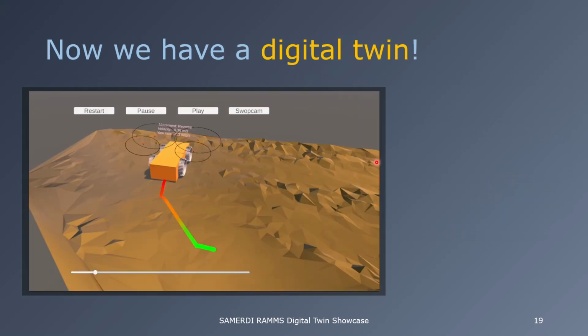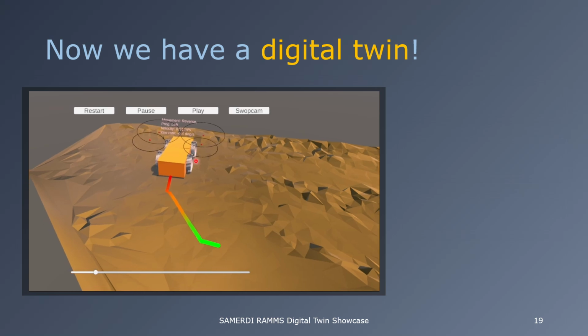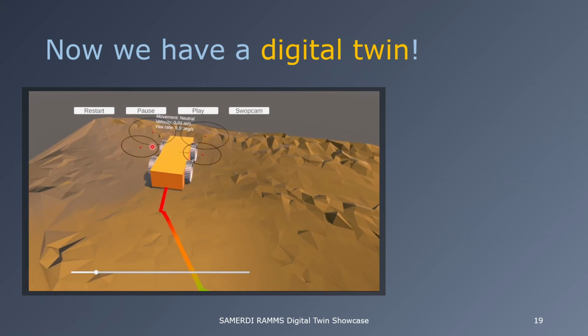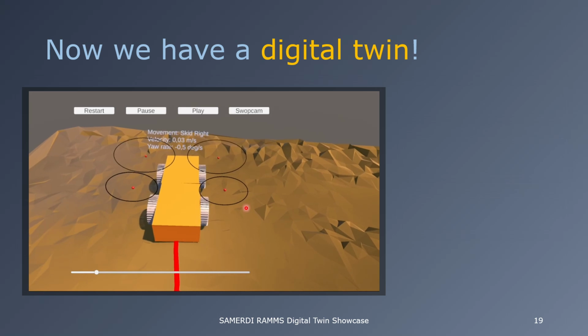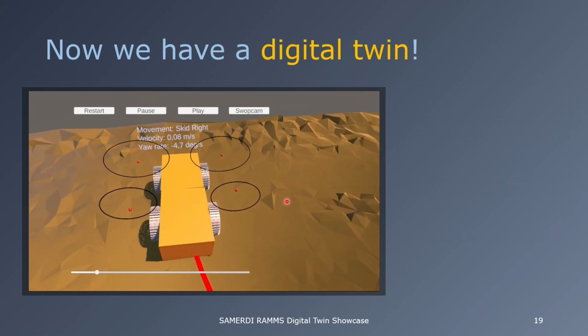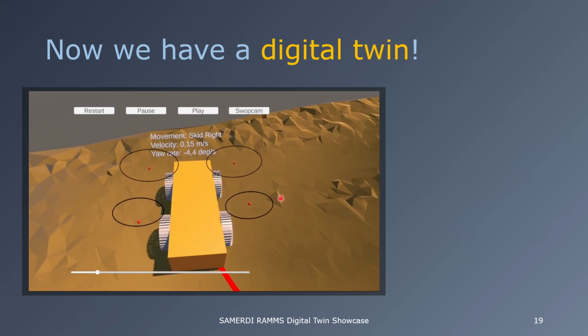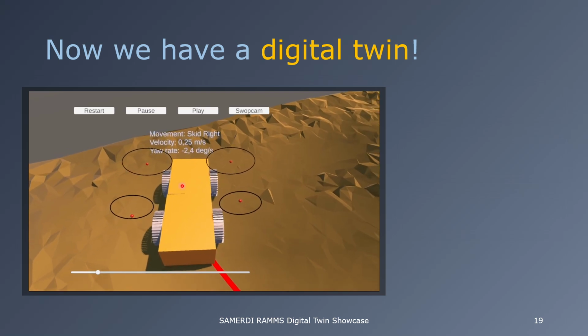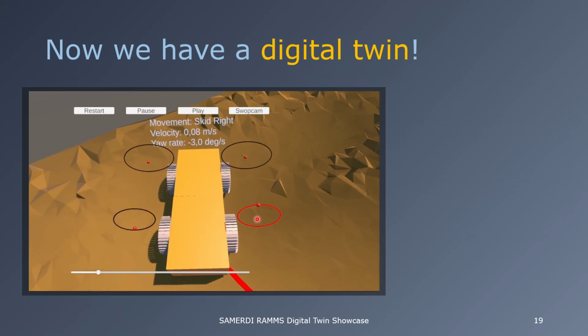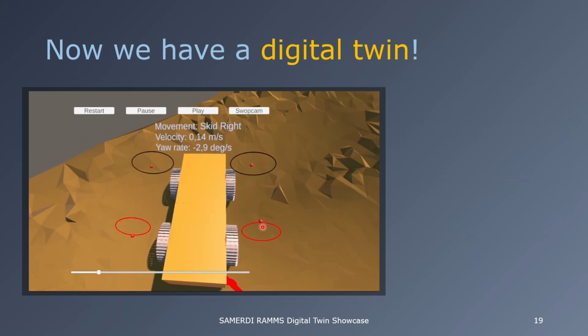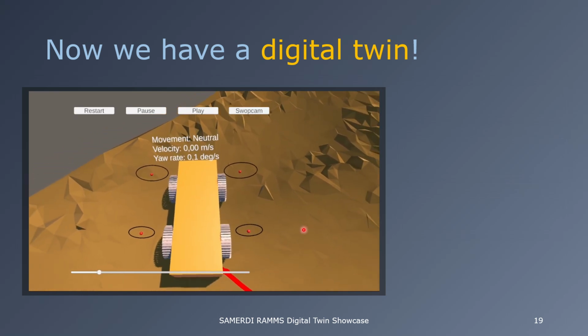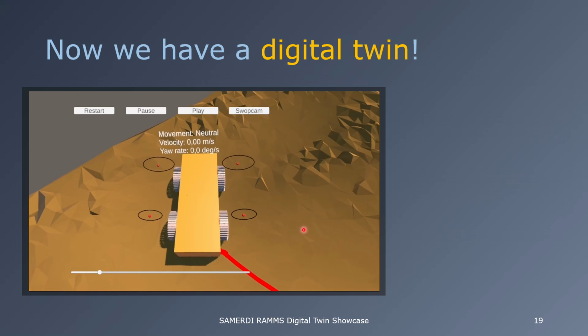Okay, so now what we did is we took this same continually updated model that I previously showed you, but now we overlaid these traction envelopes as well as the currently used up traction points. So you'll see as the vehicle moves, these points move around because traction is being used up, but also as the vehicle moves around, the traction ellipses update. So you can see they're actually shrinking quite slowly because traction is being updated as the vehicle turns. And you can see when this dot nears the envelope, it actually goes red, warning the operator that your wheel is about to slip.